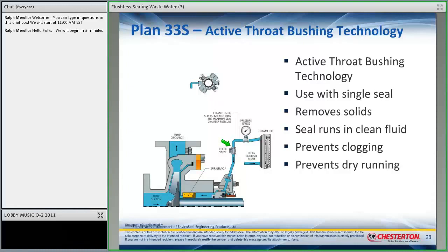I was out in California and I was talking to some of the folks out there, and what they were doing in some of their pumps, some of their seals, is they had a timer. So when they started the pump, this flush fluid was on for about 20 minutes, and then it shut off. And then when it stopped, it ran for about 20 minutes, cleaning all that area out, and then it stopped, right? So that was sort of the alternative to this, right?